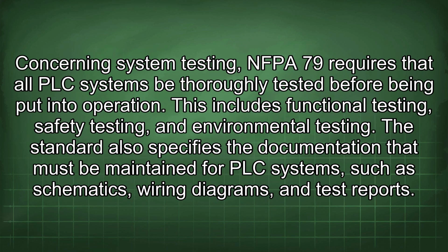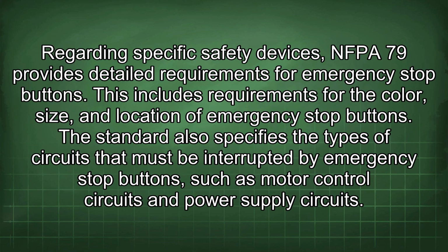Concerning system testing, NFPA 79 requires that all PLC systems be thoroughly tested before being put into operation. This includes functional testing, safety testing, and environmental testing. The standard also specifies the documentation that must be maintained for PLC systems, such as schematics, wiring diagrams, and test reports.